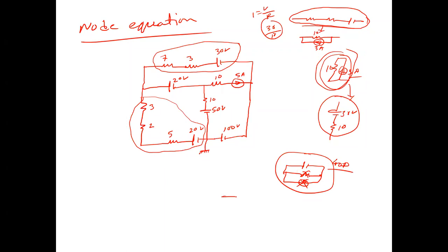If a current source is in series with any node, any voltage, any load or any source, suppose this is the current and this is our voltage source in series, then the series portions, this and this, are all omitted if the current is in series.